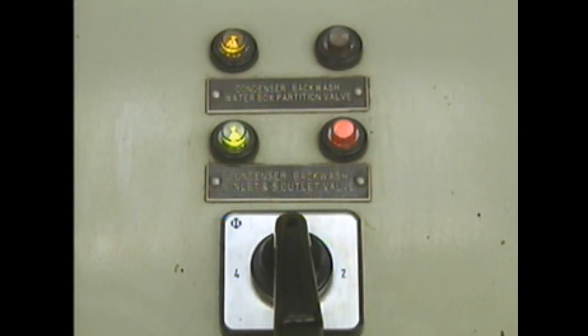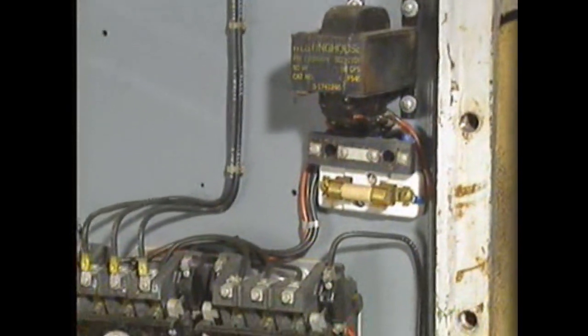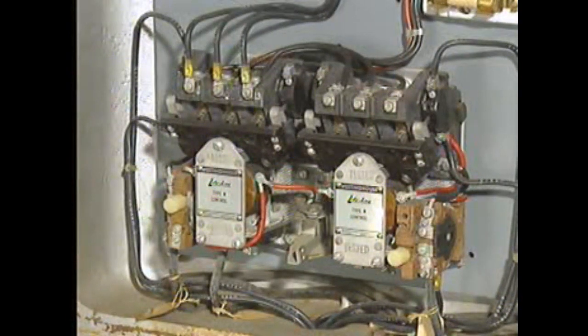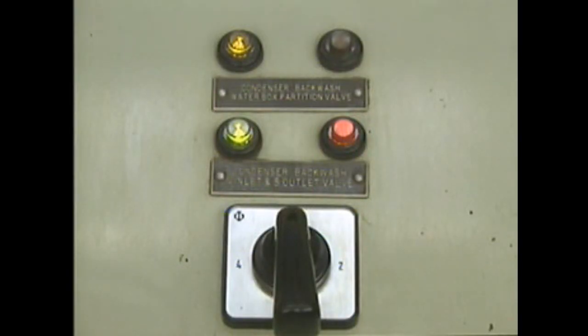of adjustment, or the switch might not be actuating because the valve isn't completing the stroke when it opens or closes. If both indicator lights for a valve are out, the technician should follow approved electrical troubleshooting procedures to identify an apparent problem in the motor operator's electrical supply circuit. But in this case, both lights are on, indicating that electrical power is okay and that the valve started to open or close. Something stopped valve movement before the stroke was complete.